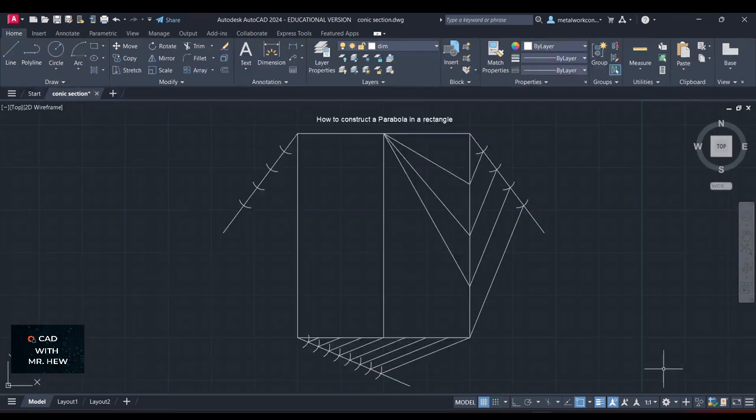Okay. All right, so we have started the procedure to divide this line into 4 equal parts, right? So we have 4 arcs. We have drawn this line, which would have been a random line, and then you mark 4 arcs, all right? So the next step is to draw a line from this point to the end there, the same procedure as what we did on the left side here.